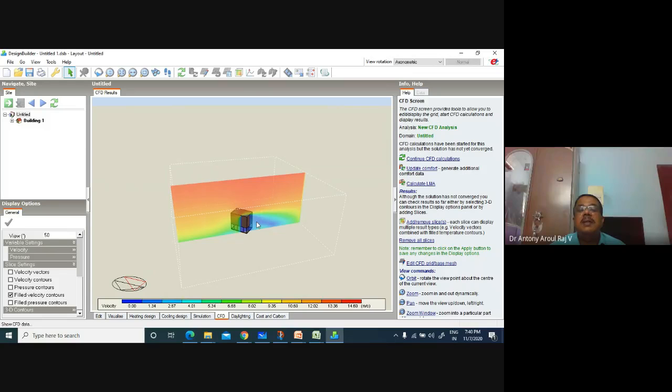Now I am getting the pressure distribution and the velocity distribution. What equations have we solved? I have solved the continuity equation and the momentum equation. From that I get the pressure and velocity distribution. Velocity I should get in the 3 directions. In advanced solvers you can go and see all the velocities individually.